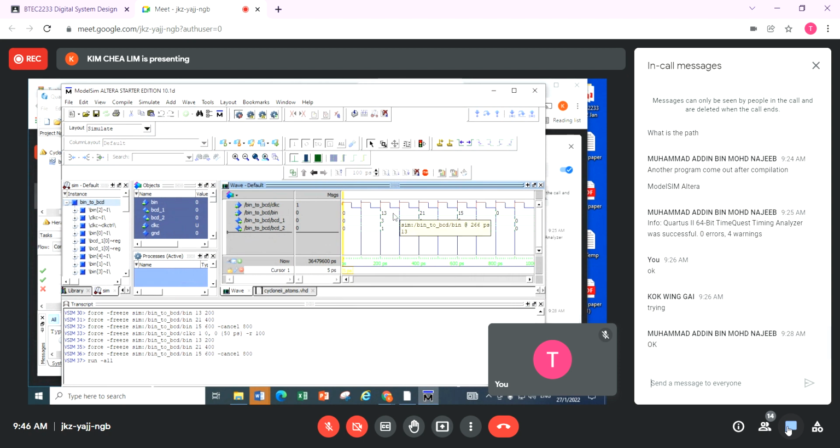So you are going to find my list program here. I input a decimal number of 13. They break this 13 for me into 1, 3. This one indicates 10. This one is a single digit. If I put 21, you will see 2, 1. Of course, you can put in more values. So here I put 15, and they give me 1, 5. All this happens at rising edge, because I say under the rising edge I want this to operate. It is based on your program.